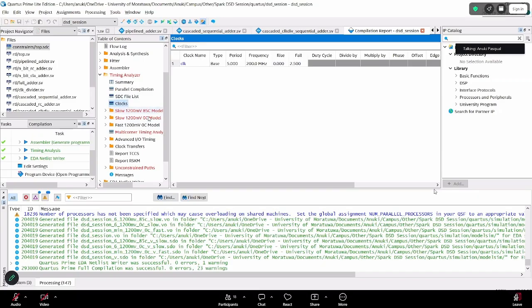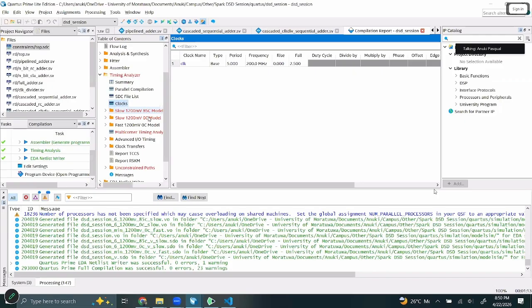There are libraries that give, for this AND gate, the propagation delay is this much under 85 Celsius and this much under 0 Celsius. It's checking a few extremes, because if it works for extremes, it should work in the middle. So let's check one of these. If any of these are failing, it's good to fix them.